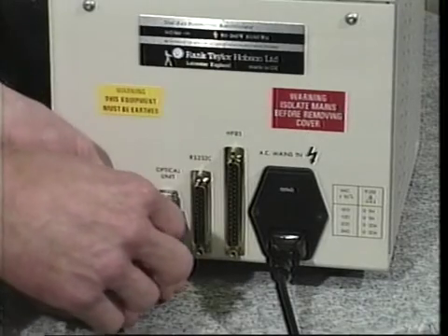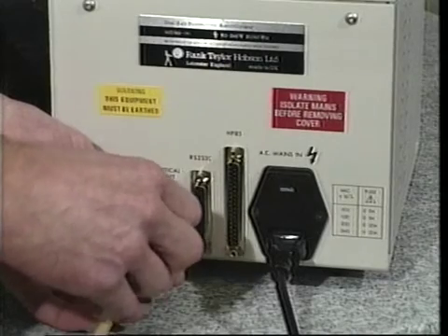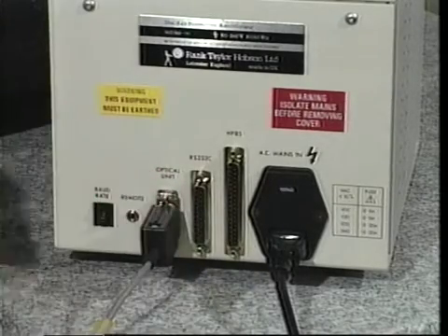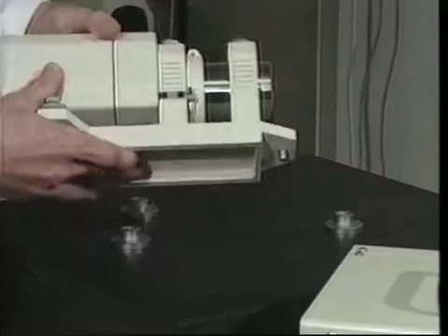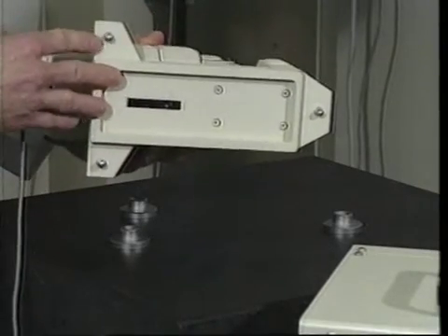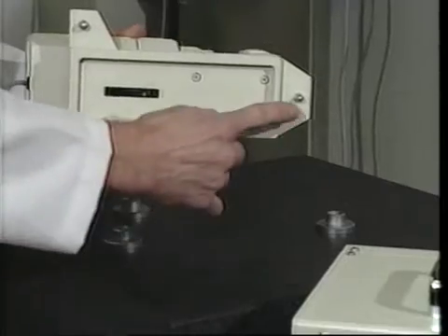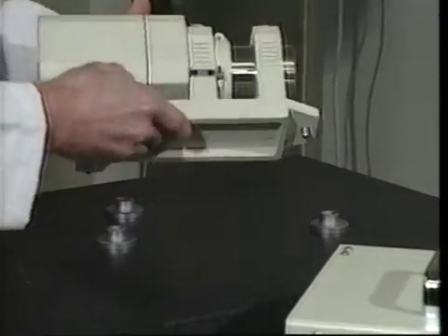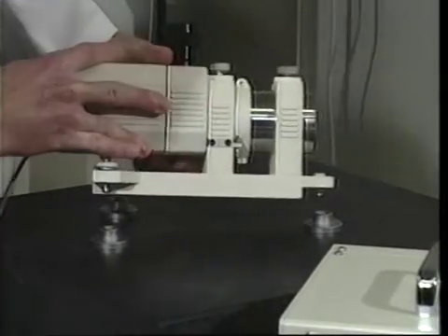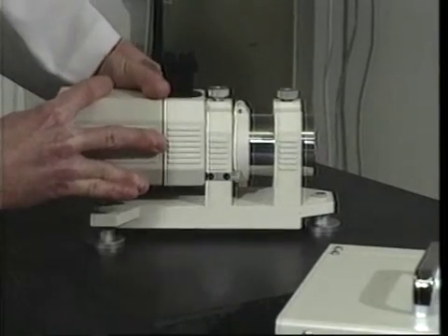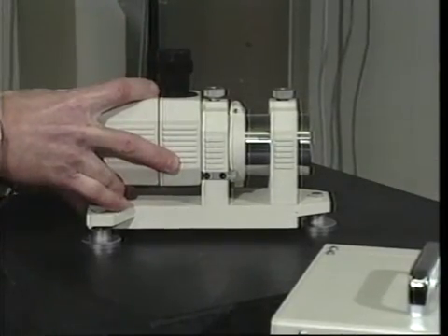To use the autocollimator, first connect the optical unit's cable to the appropriate connector on the rear of the electronic console. Place the optical unit on the 3-foot pads as shown. Note the use of kinematic mounting as the optical unit has 3 spherical feet. Kinematic mounting avoids overconstraint and the resultant lack of repeatability.